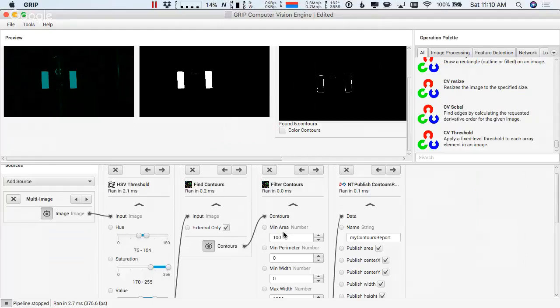Okay, but conventional wheels don't go sideways. So if you've got a game where you don't expect it to be getting pushed around and you don't expect to be having to go uber fast, and you want maneuverability instead, if you're looking at the game and you say our highest priority is to have a very maneuverable robot, more than a strong pushing robot or a fast robot, then these work great. Okay, but if you've got that other stuff, then you have to consider that.